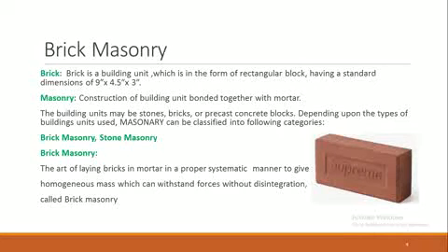So in today's lecture we will be talking about brick masonry. So what is brick? Brick is basically a masonry unit usually available in the form of rectangular blocks and having a standard dimension of about 9-inch length, 4.5-inch width and 3-inch thickness.